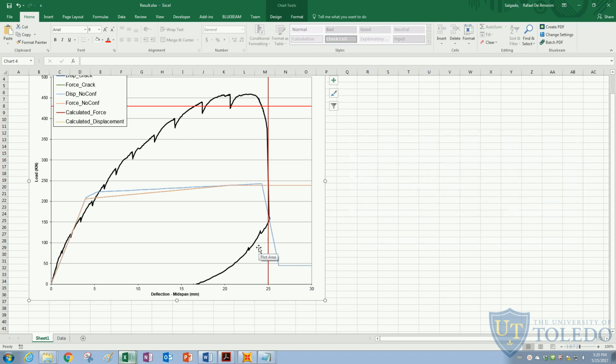The reason for that is, like I said before, that confinement properties that change the stress-strain response of the concrete only affect the fiber hinges, which is the moment-axial hinge. And since this beam was mainly governed by the shear hinge, the difference that the confinement caused in the moment properties of the hinge doesn't change anything in the shear resistance of the beam.